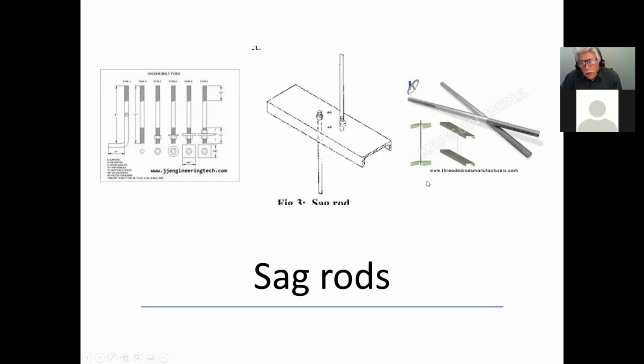So that's what these things do. They're used to make sure that our girts, which tend to sag under their own weight, can be put nice and straight, so when they come to apply the wall, they'll stay nice and straight. In terms of strength, they don't necessarily do anything. It's not going to affect the strength of the member. It's just that aesthetically, people like to see things built relatively straight, and that's what these things are.